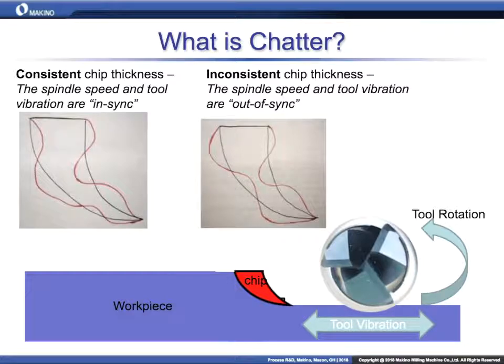Now, what's interesting here is on the left, you've done something with the RPM to get those two frequencies to match, right? Yes. And so you're going to walk us through now. If you know the frequency that your tool is vibrating at, you can adjust the RPM and get this in line. In fact, we were talking that this is what you've seen machinists do for years. You can hear it when it's bad, and they can adjust the RPM.